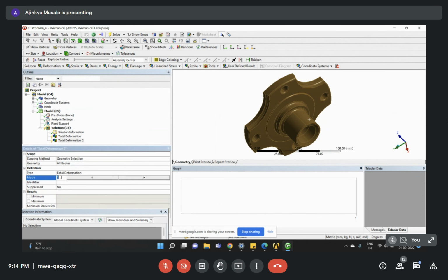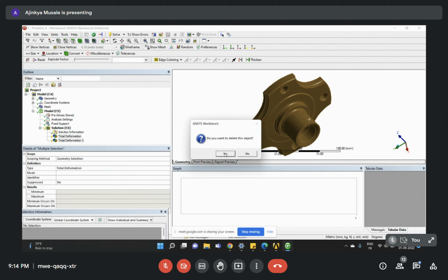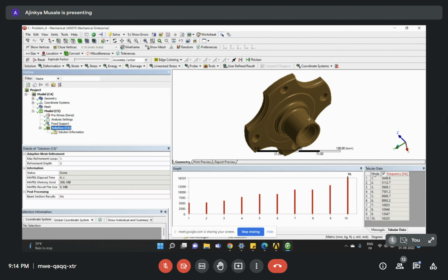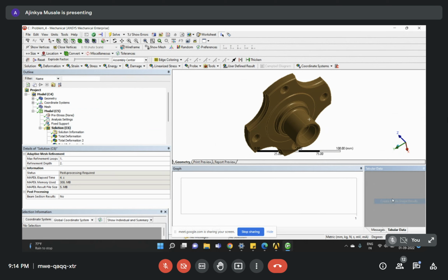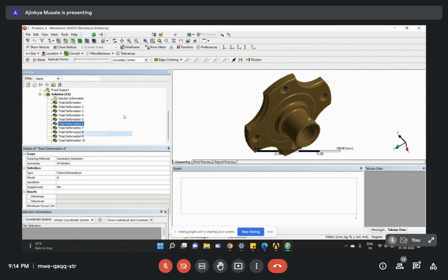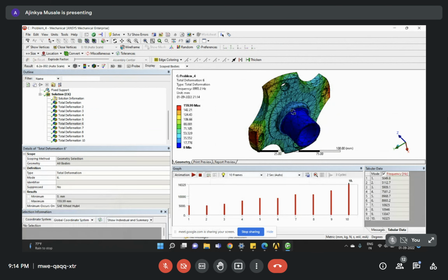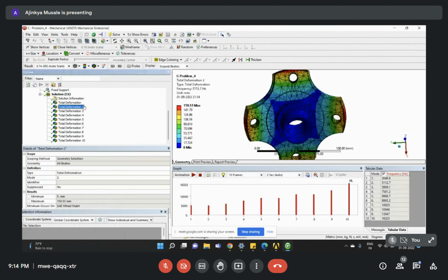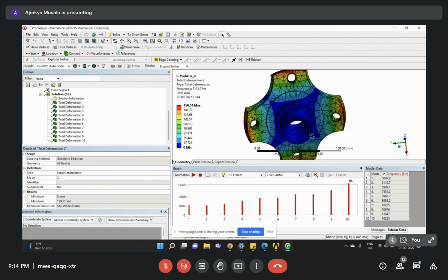After duplicate, you can simply change it to 2. So the same things are happening, what I am doing from that table, copy and create mode shapes. So you can do it here, but this is a little bit tedious. So this is somewhat simpler one. So just right click and say create mode shape results and say just evaluate. Fine. So here we have results for the different frequencies. So these all are the natural frequencies.